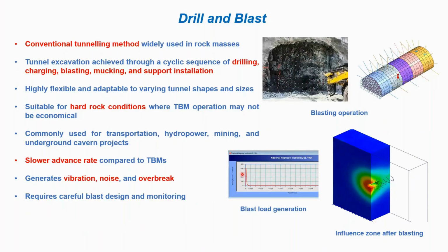Based on some input parameters related to explosives, like the explosive borehole diameter and some other variables as inputs, we can actually create this kind of blast load and apply it in the analysis. And then we can assess the influence zone after each stage of excavation through the blasting.